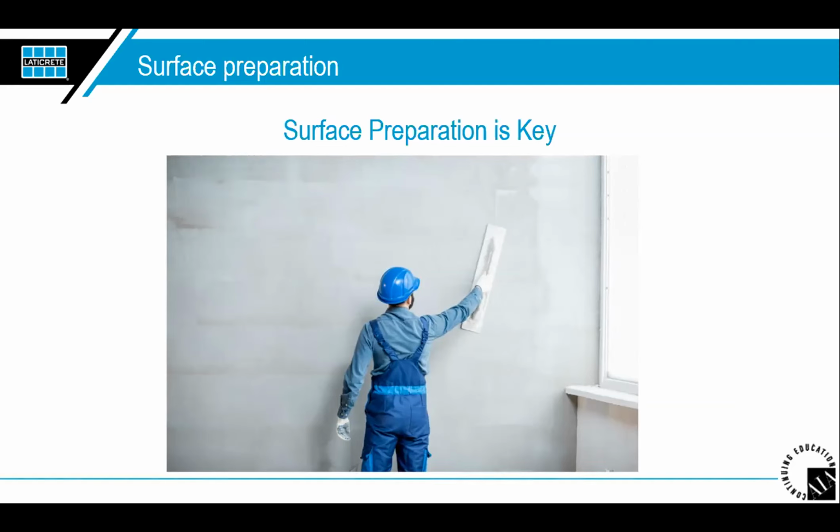They have a great video on the TCNA page, and it's on YouTube as well, where installers will sponge down the tile, which is a correct procedure, but by putting too much water in the installation itself and setting the tile too fast after that, as soon as you set the tile, you feel that you have a great bond, but you'll pick it up and there will be no thin set whatsoever stuck to the back of the tile. So could water be a bond breaker? Yes, it definitely can. But going back to the substrate, the substrate must also be suitable for tile installation, and in the environment that it's going to be located.